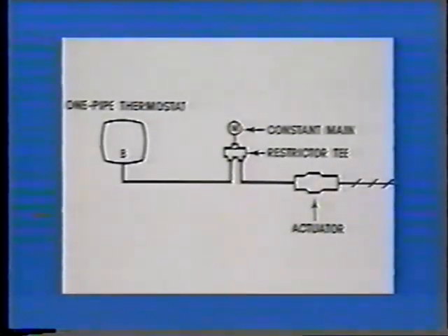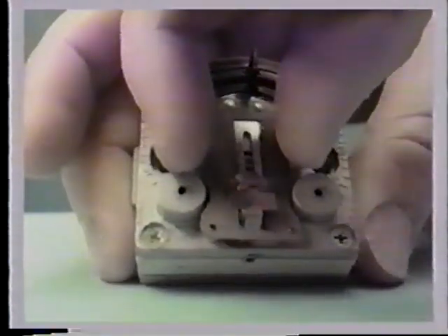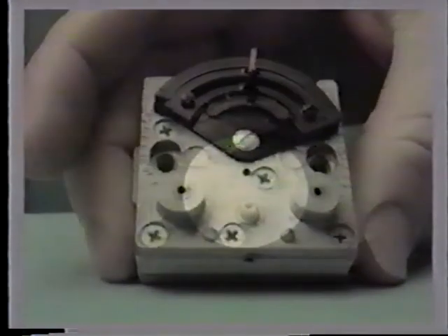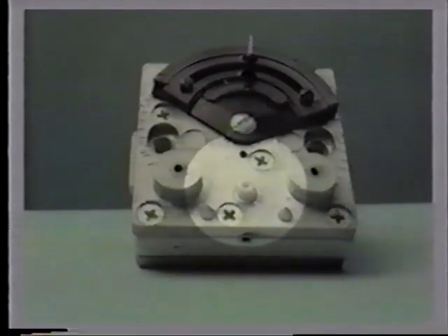This type of thermostat is referred to as a bleed type thermostat because the thermostat itself constantly bleeds air pressure to the atmosphere. The constant pressure main air supply is fed through a restrictor into the branch line between the actuator and the thermostat. An orifice in the restrictor limits the volume of air supplied to the thermostat and actuator. The thermostat opens or closes a bleed orifice to bleed off or build up pressure in the branch line to the control device as dictated by the space temperature.